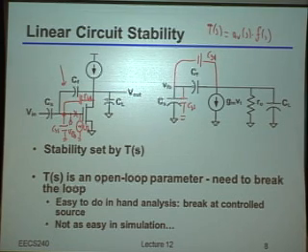And if you look at the small signal model, that's done purely by, instead of having this GM driven by VFB, I just split those two out. I drove a test source right into the GM, and then measured the feedback that would have come back into the GM. Does this make sense to everybody?